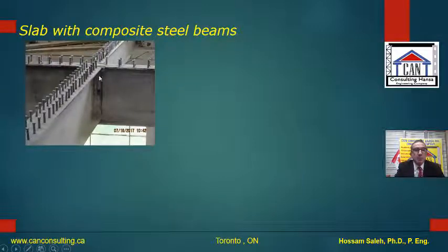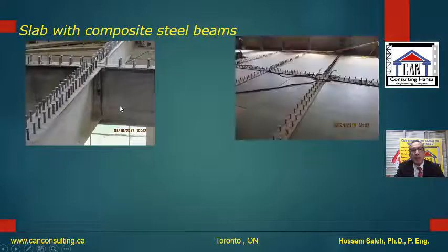If you have a steel beam like that with the connection here, you can have the concrete floor if you provide a formwork and then the steel reinforcement. Your slab in this case will be a one-way concrete slab supported on these two beams, with the main reinforcement in this direction and the minimum reinforcement in the perpendicular direction. So that's the way of having a concrete slab on a steel beam with steel studs.